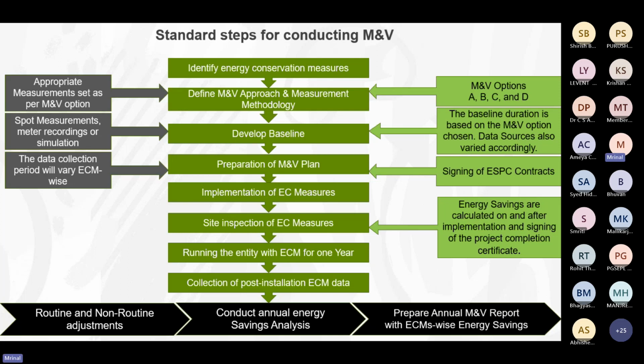Now, once it is signed, then you have to go for the implementation of the EC measures. Then after the implementation, you have to do the inspection of the EC measures. Inspection means you have to do the verification process of those EC measures. As defined in the M&V plan, you have to adopt the same methodology as you have adopted in the baseline period. Same formula, same interval of data recording, everything has to be the same.